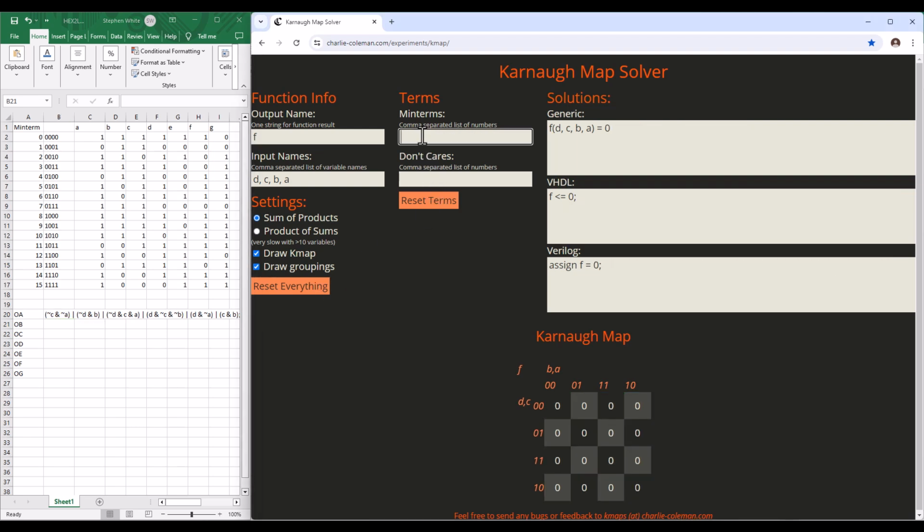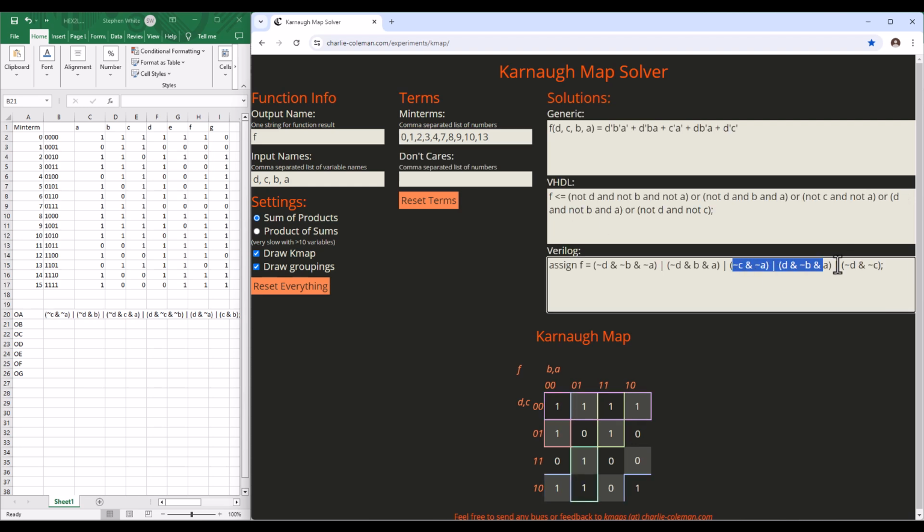I will now demonstrate our shortcut by entering the minterms for segment B. As we did for segment A, I just list each of the input values that result in segment B having a value of 1. As mentioned, there needs to be a little cleanup to get the Verilog form of the equation into the CUPL form.